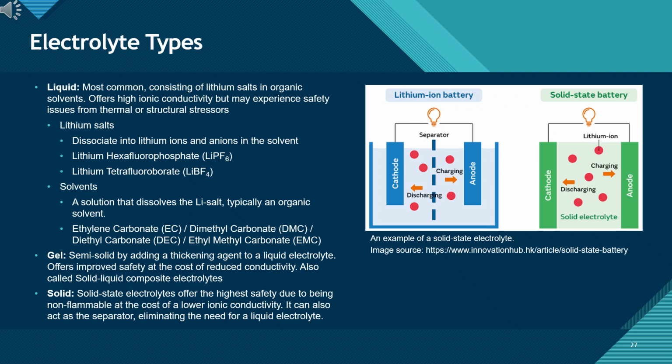Types of electrolytes. On this slide, we categorize electrolytes into two main groups, those we use today and those we might use tomorrow. The industry standard right now is liquid electrolyte. As you can see on the left side of the diagram, this consists of lithium salts, most commonly LiPF6, dissolved in organic solvents such as ethylene carbonate. Because these solvents are liquid organic chemicals, they are effective but come with risks: they can leak, and they are flammable. This is why our safety protocols regarding fire prevention in the electrolyte filling area are so strict.